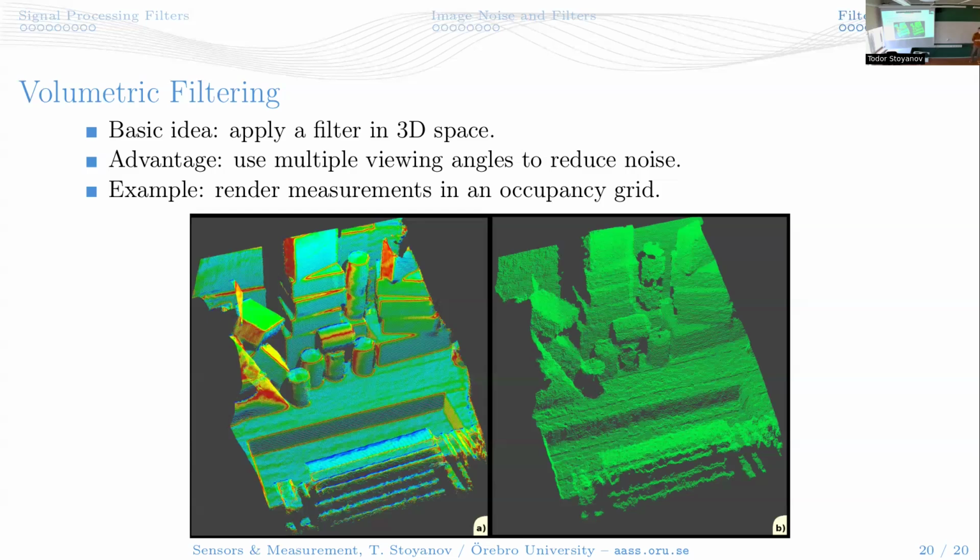And for each point here, I'm going to calculate a value. If that point is outside of the object, I'm going to give it a positive value. And if that point is inside the object, I'm going to give it a negative value, right? And if that grid point just happens to be exactly on the surface, its value is equal to 0. So instead of representing the surface directly, we have this implicit way of representing it.